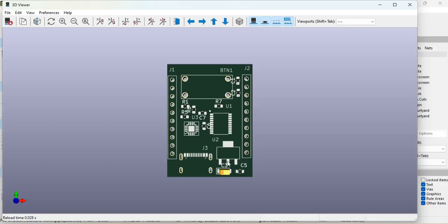There is no rule that you must have the ref des indicated on the PCB. You find many PCBs, that too dense PCBs, without the ref des printed on the silkscreen. That is to save space and increase the component density on the board. So in such cases, you can take that call, and generally the assembly drawing will be used by the designers to get to know the component reference, or one can open the PCB layout and check the components.